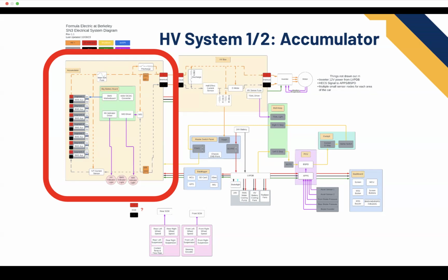All right then. Starting with the high voltage system, there's two main physical locations that you will encounter high voltage. Really four main, but two of them are the inverter and the motor. Those should not be opened. Those should be closed systems, because the inverter and motor are the only two circuit components you could say that we purchase completely assembled. So you may be inserting harnesses and stuff, but those should not be opened. But they do still have high voltage associated with them, and you do need to be careful of that.